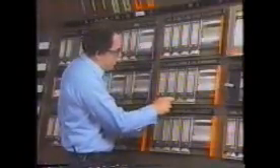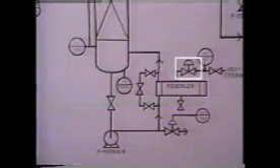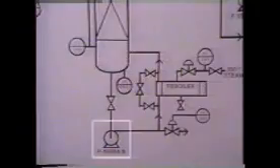The inside operator sets the temperature controller to 0. This closes the reboiler steam valve. This stops heat going to the column and halts the distillation process. The recirculating pump at the bottom of the column is left on for a short while to help cool down the mixture. Meanwhile, the inside operator moves the set point of the bottom's takeoff flow controller to 0.